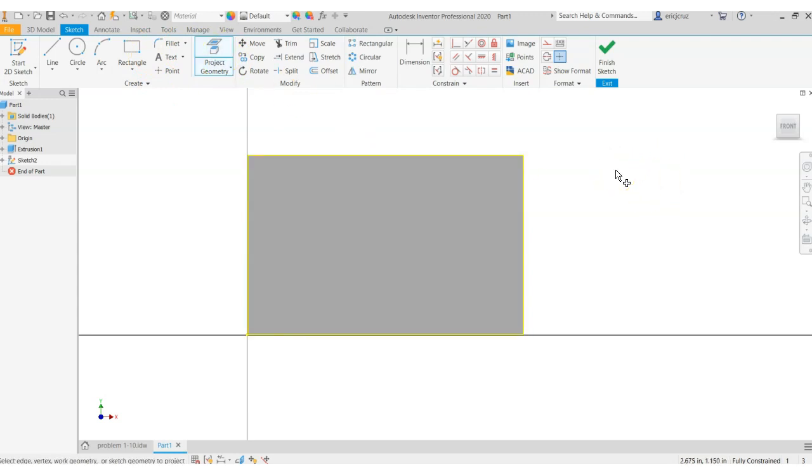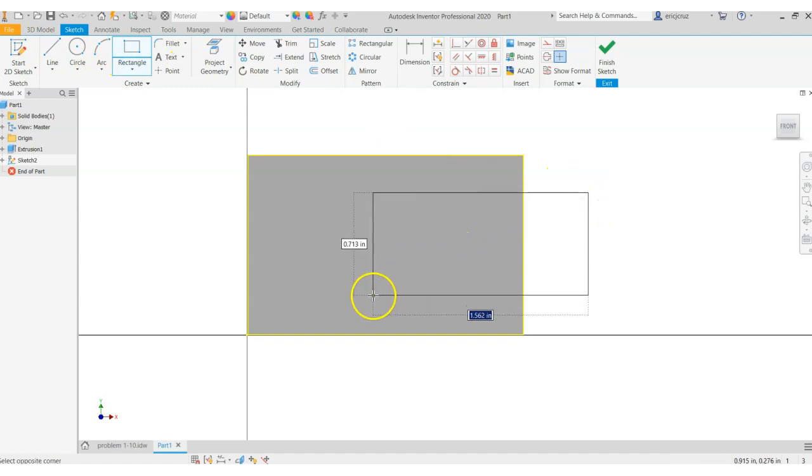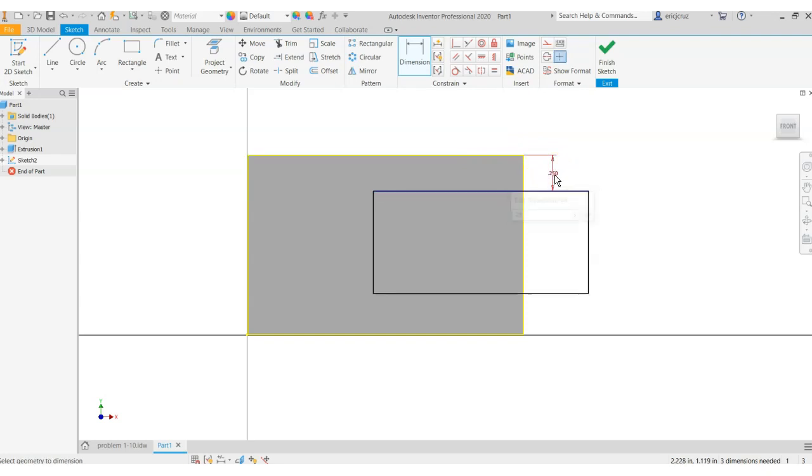That just makes life way easier when you're extruding material. And we are going to start by drawing a rectangle with no dimensions so that it's touching the part and also hanging off of the part like you see here. Click dimension, click the top edge, and click the top line of that rectangle. That's going to be 0.25. And the same dimension on the bottom,